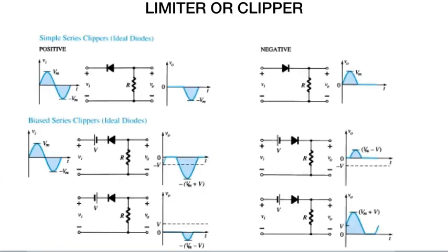Now, looking at the limiter or clipper, what does it actually mean? A limiter limits or clips the input voltage to a desired output voltage, and beyond that no more voltage will be passed through the device. As you can see, there are various clippers, but let me look at this one because it is the most intricate one, I feel. The same logic applies to every other clipper.